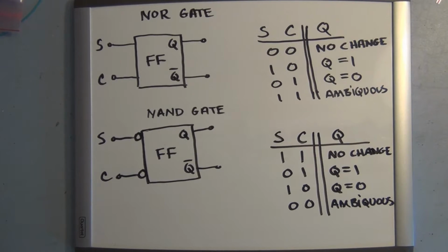In the video covering flip-flop theory, basic Set-Clear flip-flops, we ended with the logic symbols for both a NOR gate type Set-Clear flip-flop and an AND gate type Set-Clear flip-flop with their accompanying truth tables. But it was mentioned that flip-flops can have multiple inputs, and so far we have a set and a clear. But we're going to introduce a third input, and that's a clock input.